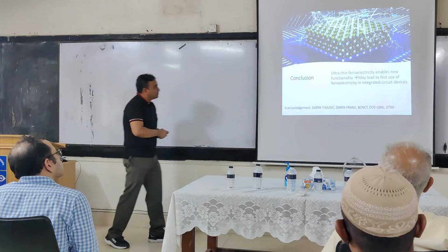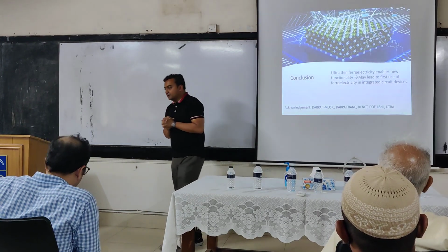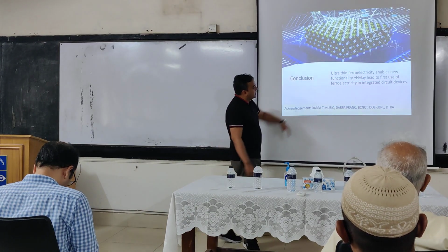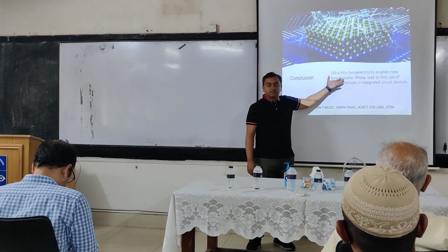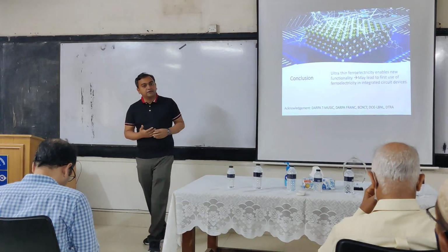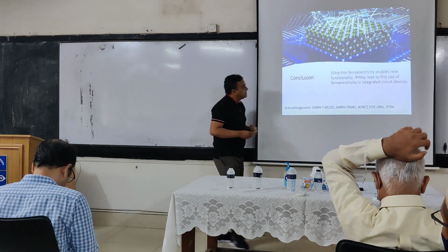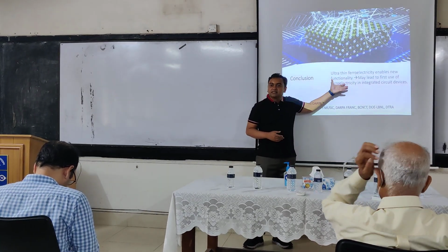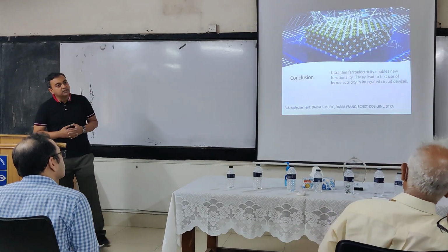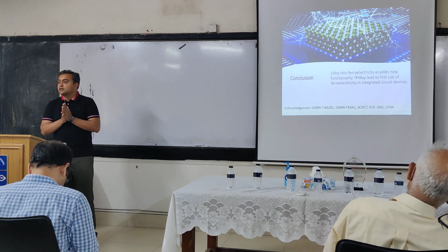So basically, we have been working on negative capacitance for some time as a physical concept. We think that the phenomenon is established, with very robust grounding now. The main question, until 3-4 years ago, was whether the ferroelectricity was in materials that we can put on transistors. But now we have these very thin ferroelectric materials, even down to half a nanometer, right? And that I think is going to lead this technology into integrated ferroelectric devices, because we now see that we have materials that we can put on advanced silicon transistors, and we can actually do better than advanced silicon transistors. So on that point,